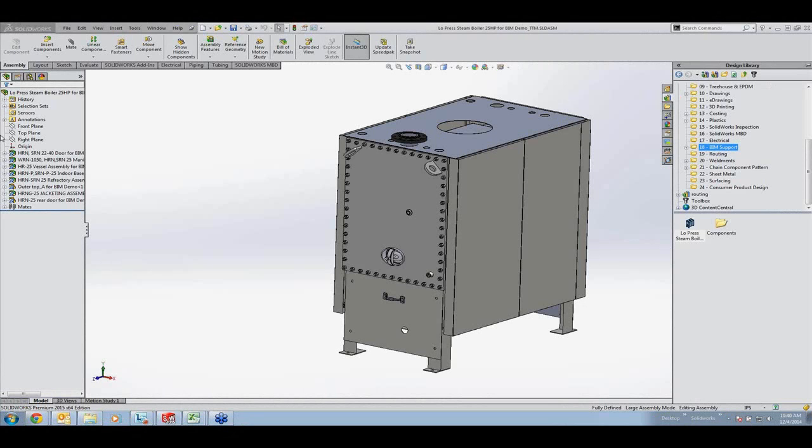Also, the corner treatment has been enhanced. Same functionality, but now the pop-up menu is easier to read. In the past, we had a drop-down here to choose between different groups, but now it's all in one window here. It's easier to select and visualize with the preview here what's going on. So in this case, I can change the trim order to maybe 3. You can see how it's going to modify my weldment there. Green check mark in the box. And very easily, I can create this dynamic cut here. Well, a very challenging cut to make by hand.